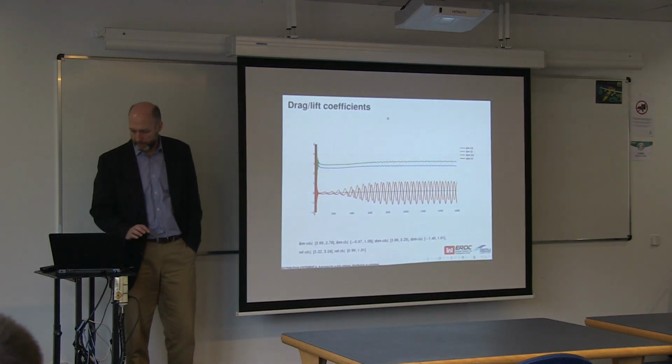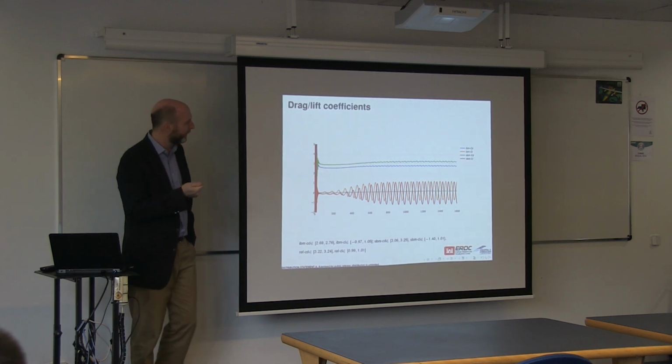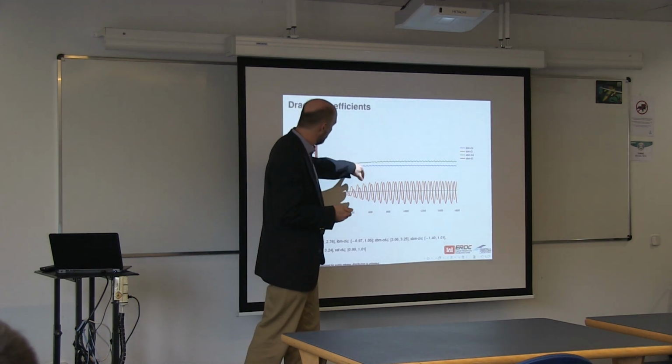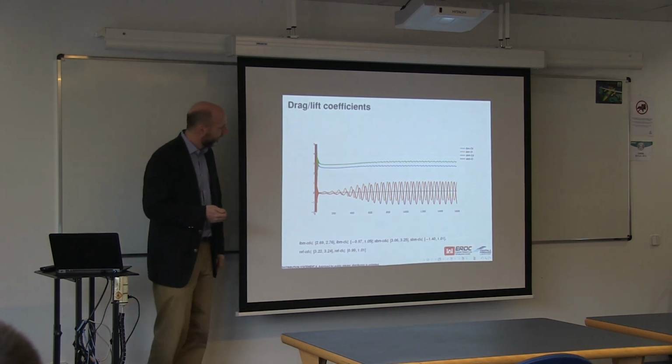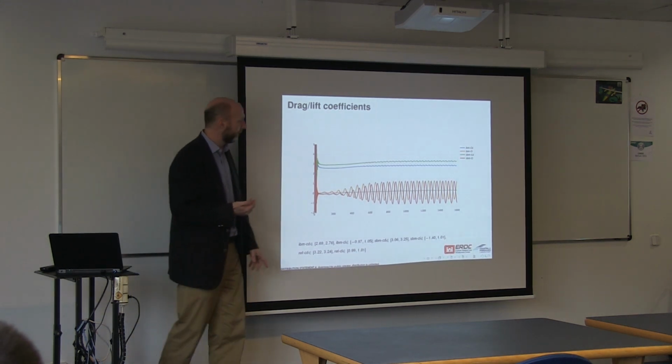If you look at the drag and the lift coefficients, here we're doing a comparison of what we get from the shifted boundary method and from the immersed boundary method. The value for a conforming method and most of the published results are right around 3, a little bit above 3, so they're closer to our IBM results. And the phasing is a little bit off on the vortex shedding.